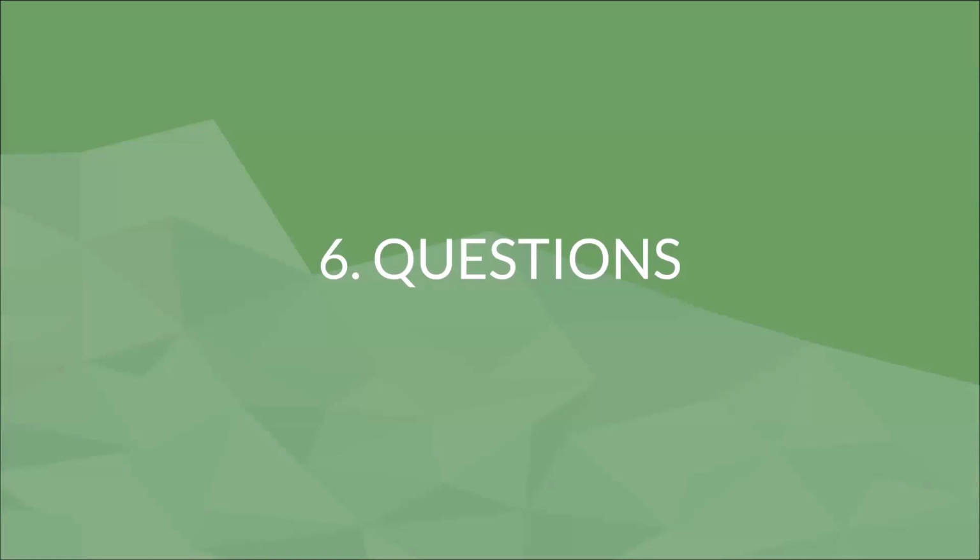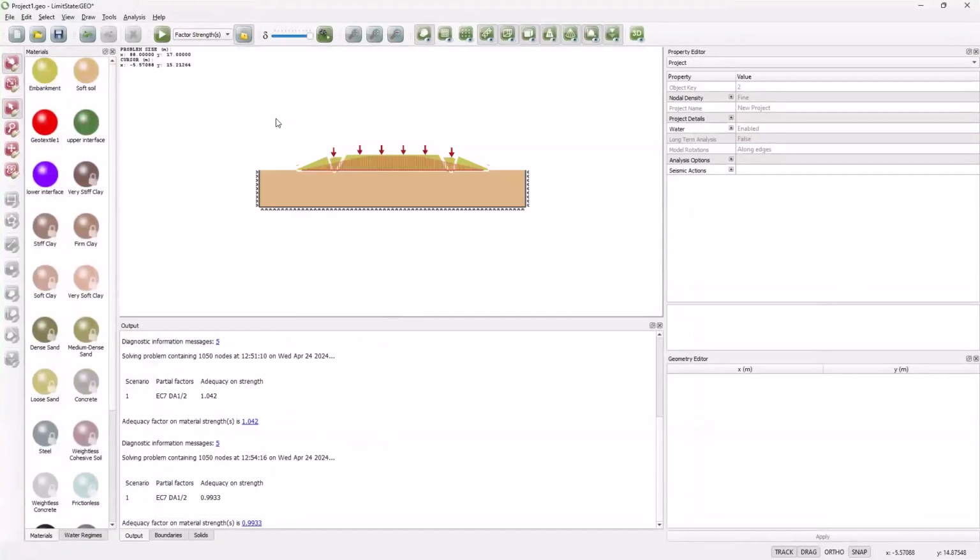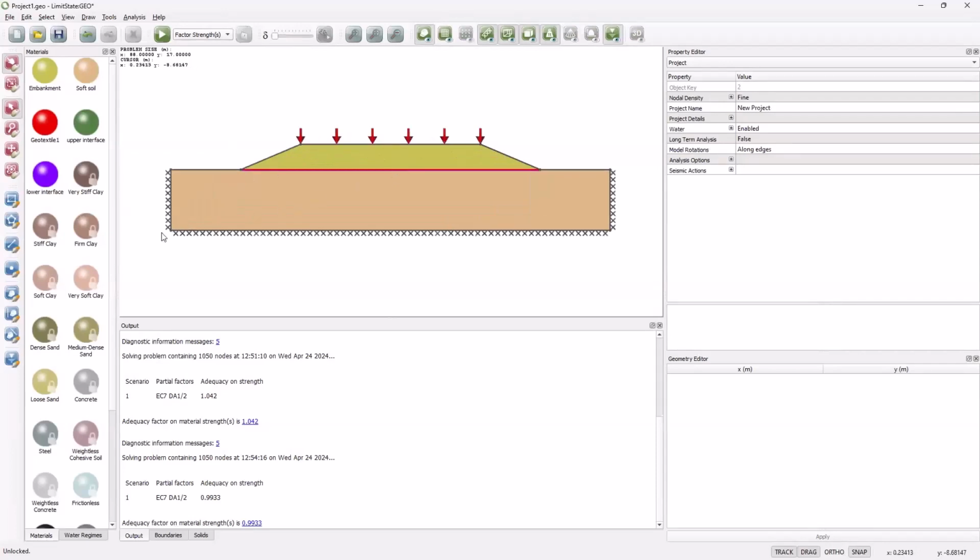How could we add water above the soil? There's another question, so we're just going to bring the software back. So the simplest way is to draw in a water table. So for example, this embankment suffered some flooding. I can draw in a, I've just got that in the wrong height. Let's try again.